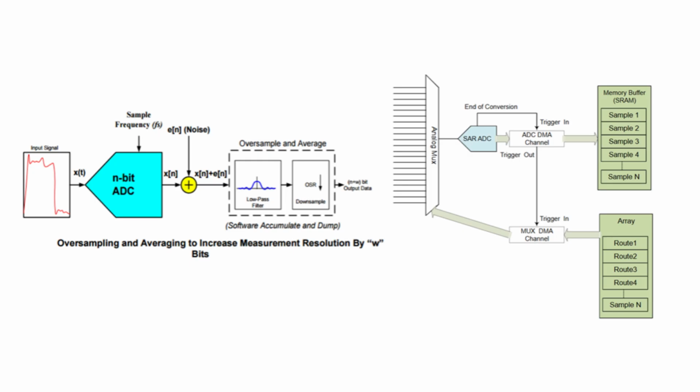That's really neat. Trading speed for precision. Exactly. You're taking 16 times longer to get 1 reading, but that reading has potentially 4 times the resolution. And you mentioned digital filtering alongside this. Yes. Digital filtering techniques are often used in conjunction with, or sometimes instead of, simple averaging from oversampling. They help further refine the signal and reduce noise.